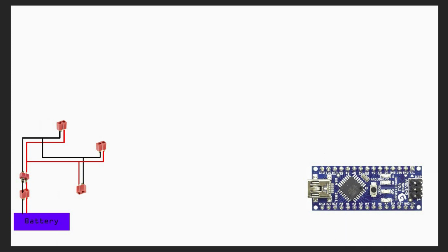Alright, so I think the last one will be the OLED display. The OLED display I'm using has 4 wires. You have to take note for this one that I'm using: check what voltage it requires. For mine it is 3.3. So basically I connect it to the 3.3 of the Arduino board, one to the ground, and two of them to the reserved pins of Arduino, A4 and A5. So this is reserved.